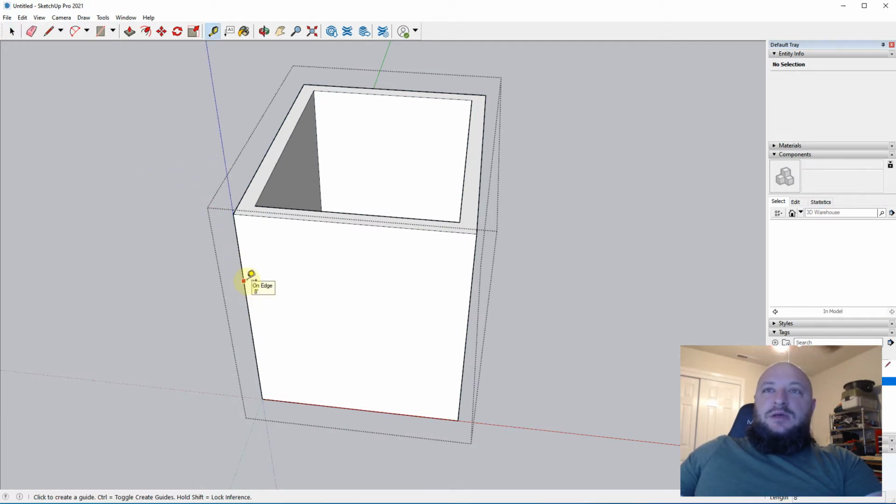and then I'm going to pull out the tape measure tool. I'm going to click, oops, of course I missed it. And I'm going to slide it. I want this door, see, I want it 6 inches from the corner here, but I'm going to measure it from the outside because it's an easier place to work. So I'm going to make sure it's going off in this red axis, hold down shift, and you can see that the red axis turns solid like that, and you know you're on the right direction.